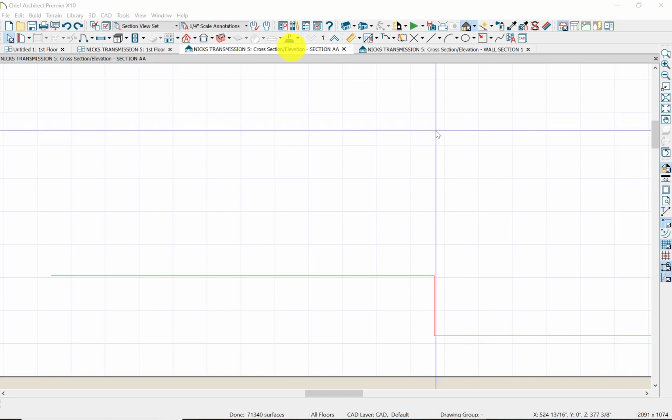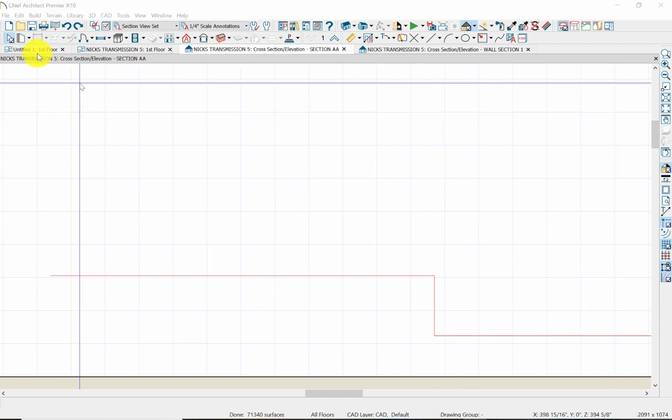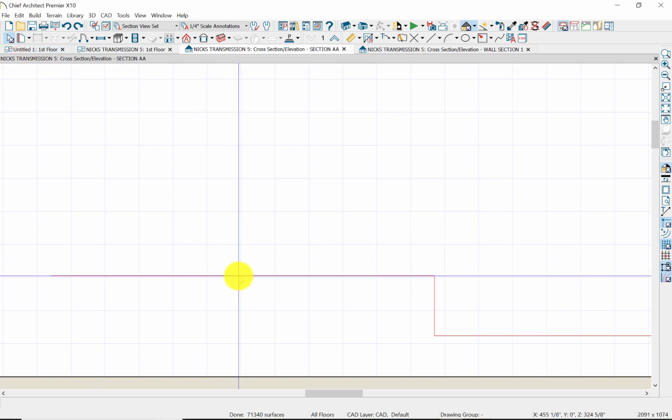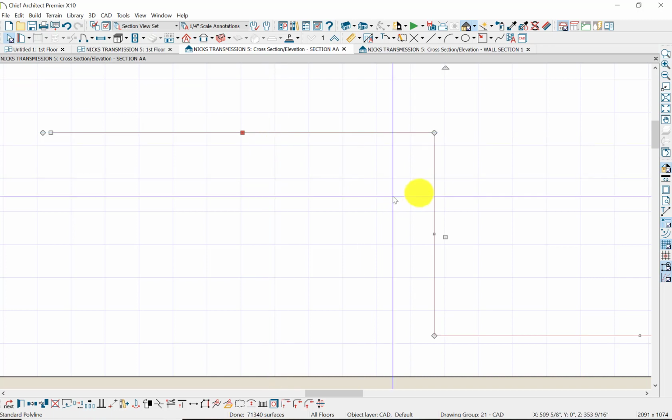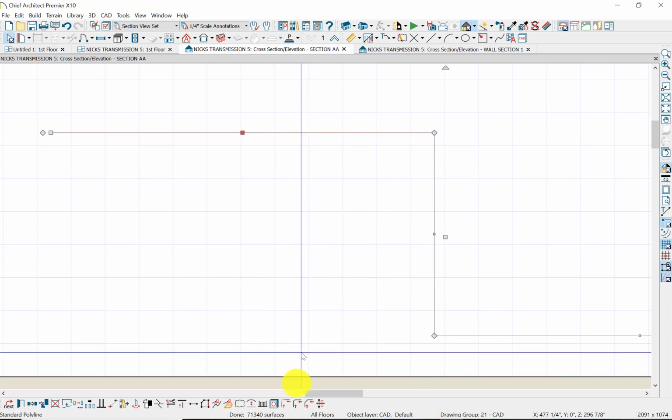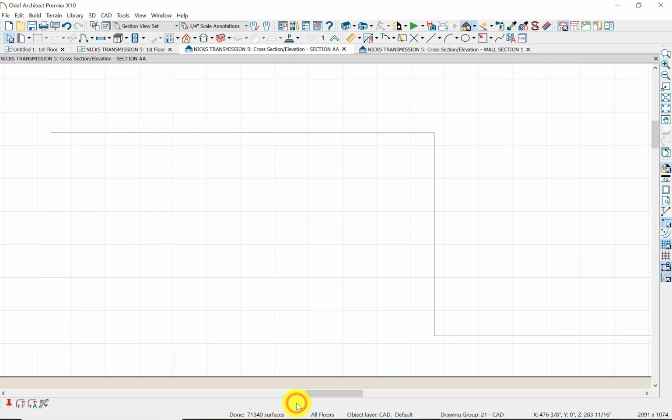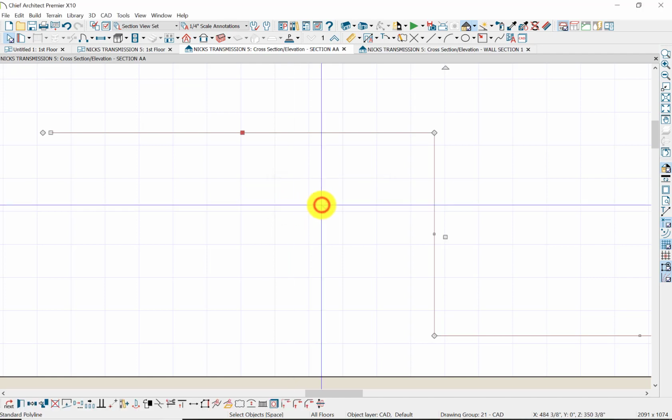Okay, let's work on the fillet command. We have our famous line, our red line. Let's stretch it up so we have a little bit more room to work on our fillet. And we've picked that line. We go to the fillet radius, fillet command. Go to the fillet radius, and 12 is nice. Just keep it there. So we've set the radius,